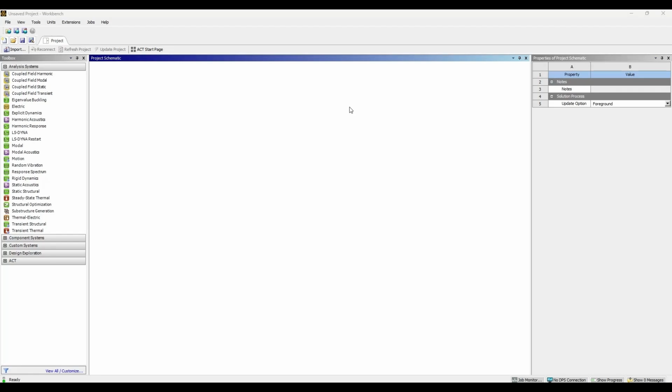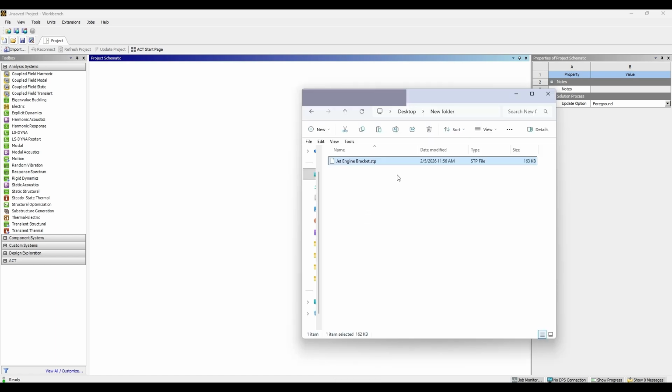Hello everyone. In this video I am going to show you how to perform topology optimization analysis of a jet engine bracket in Ansys Mechanical. So this is the Ansys Workbench platform. First, we are going to import the geometry. There are several ways you can import the geometry in Ansys Workbench. The way I prefer to do it is, this is our CAD model, just click here, drag and drop here.